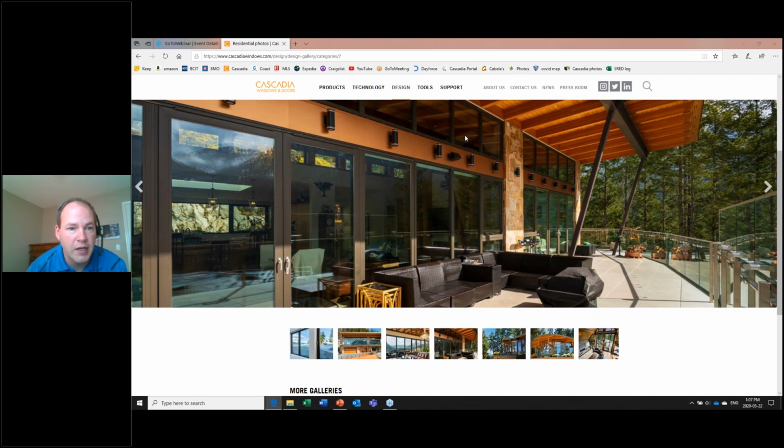Another question: might it be possible to have a window wall in the exterior wall of an exit stair that is continuous without the small spandrel sections? Of course, since there's no story within the stair. It's a very interesting question, but I don't think I'm able to answer it exactly for 2 reasons. Number one, I don't have enough code expertise to comment on that. Another thing that I'm familiar with is that in a public building, if the exit stair is on the outside of the building enclosure, that wall usually has to be a rated wall, not just a non-combustible or a tested assembly, but literally a firewall to preserve the possible use of that stair even in a fire.